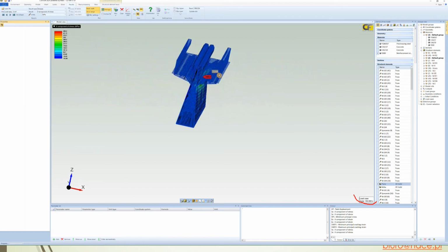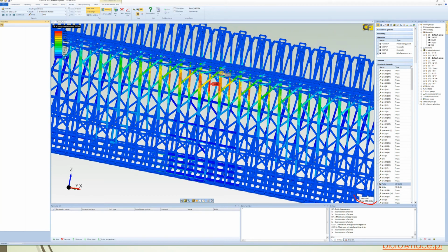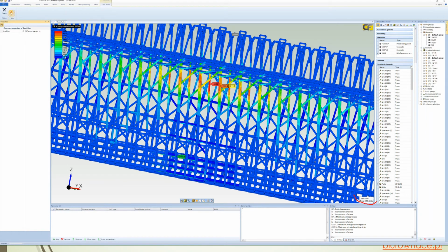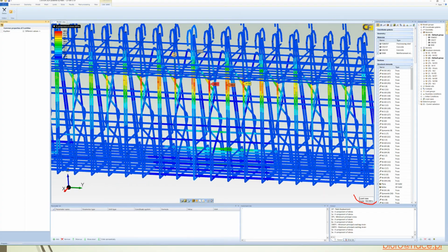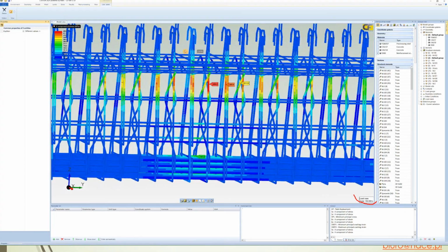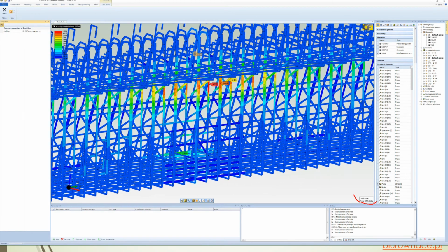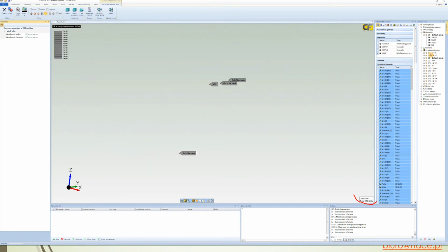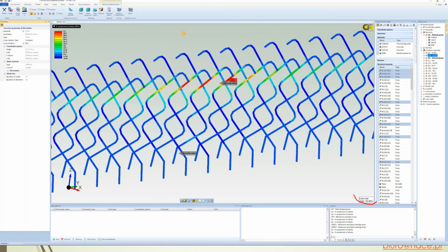Here we can see maximum von Mises stress, and we can see that even with this huge impact and the damage on concrete, the maximum von Mises stress is below yielding stress. So there is no plasticity on these rebars due to this impact. As there is no yielding and the stress on these bars is below yielding stress, we can determine that this beam can be reinforced and repaired, because it is not a very high damage, only the concrete part.